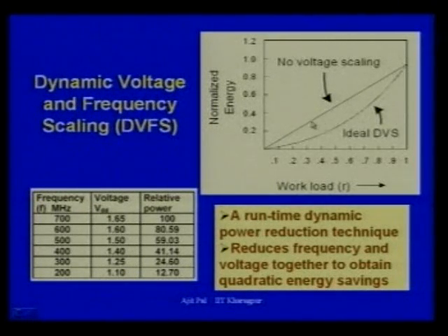That means you are not doing supply voltage scaling. You are only doing frequency scaling. You are reducing the clock frequency. That will also lead to reduction in power dissipation. But if you reduce the supply voltage along with frequency, you can see the relative power dissipation is significant.